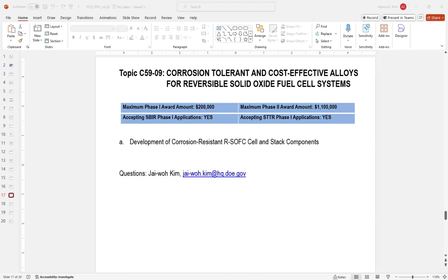But you should run under very high steam concentration, above 90%. And you have to run at least 500 hours. So you have to figure out, okay? And you also have to figure out two things: the corrosion mechanism and how to prevent it. Okay. Any questions? Yes, there's one question.